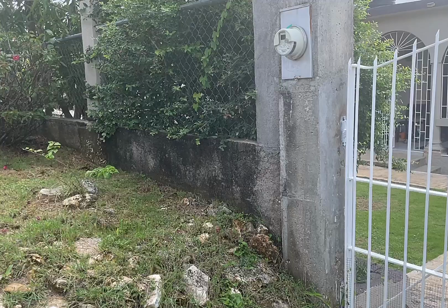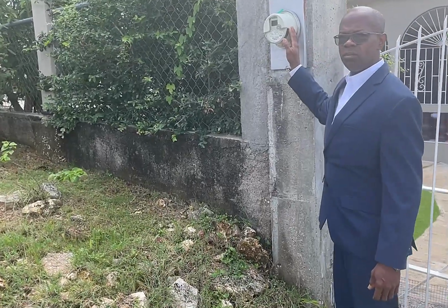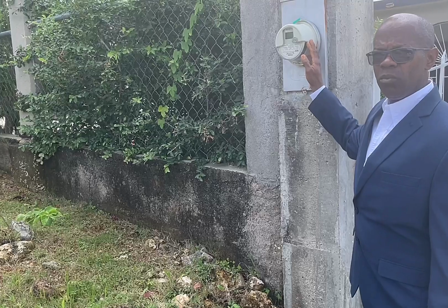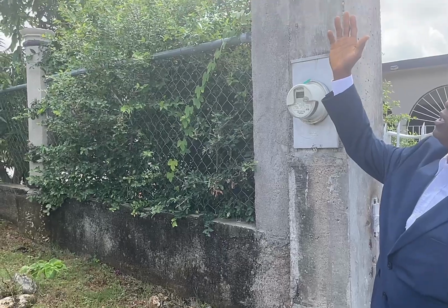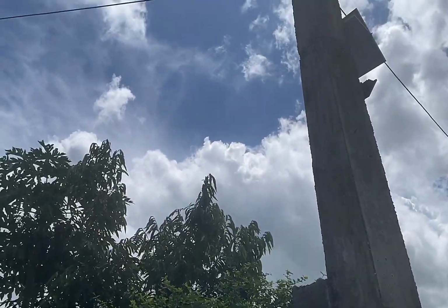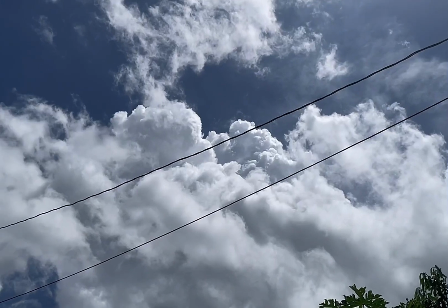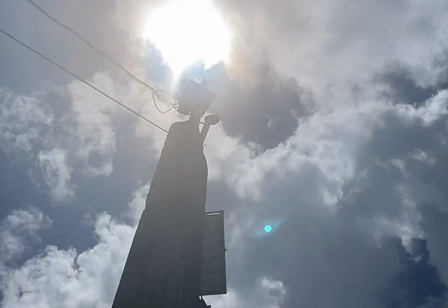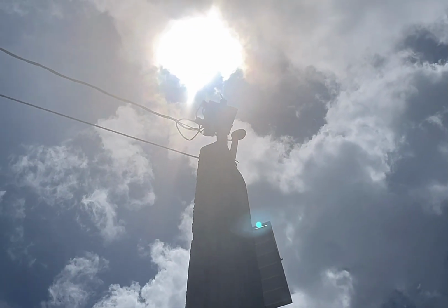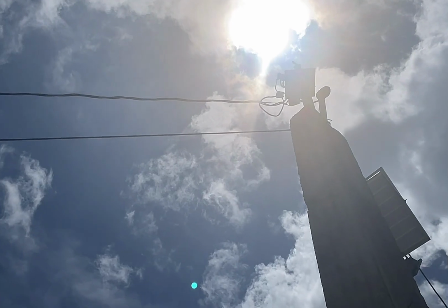And also we need to adhere to the maximum permissible voltage drop that is stated in the code. So this is one of the requirements that is met, and the utility company wants the meter, utility meter, to be accessible. And if you look, this is within the 100 feet that is required, and the stanchion is at the gate. Here we have also one electricity supply point according to the code.